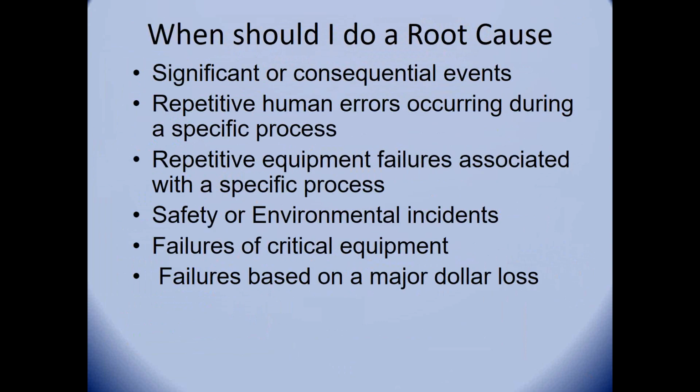A failure of a critical piece of equipment. You know, a gas turbine might be an example. If something like a gas turbine or a major piece of equipment fails, that may trigger a root cause analysis. A lot of companies I go to, they do root cause analysis based on a dollar loss. There was one where any downtime failure or equipment failure of $250,000 called for an immediate root cause analysis.